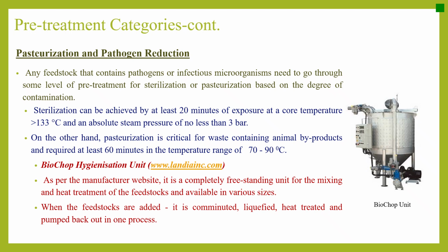One such commercially available unit is the batch hygienization unit by Landia. So as per the manufacturer website, it is a completely freestanding unit for mixing and heat treatment of the feedstock and available in various sizes. When the feedstocks are added, it is comminuted, liquefied, heat treated and pumped back out in one process. You can go to the manufacturer site and get more knowledge about this product.